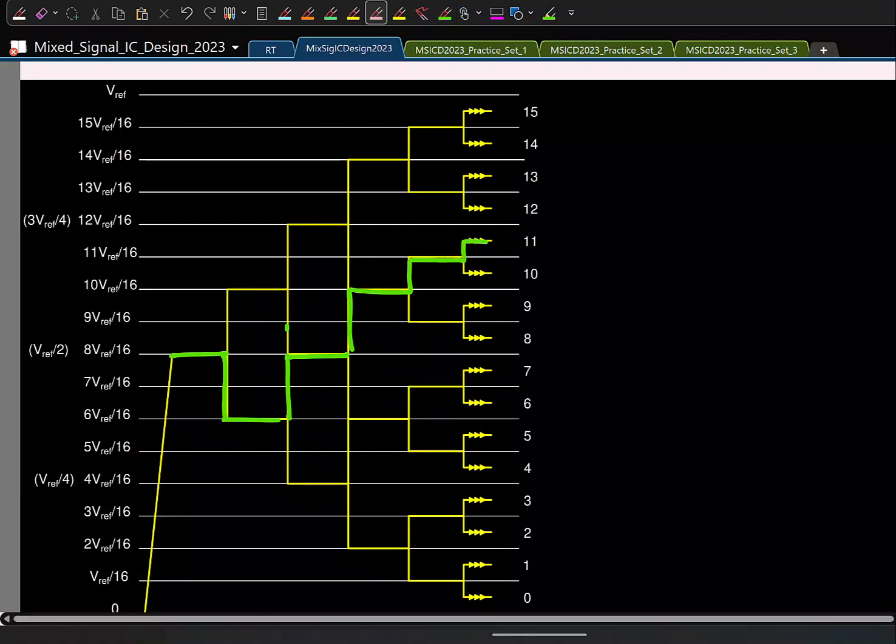As long as my input is in this range, I'll be okay. So that is again 4 steps. So the total redundancy I can have in the first step is 4 on the downside, 4 on the higher side. So 2 times 4, 8 LSBs.